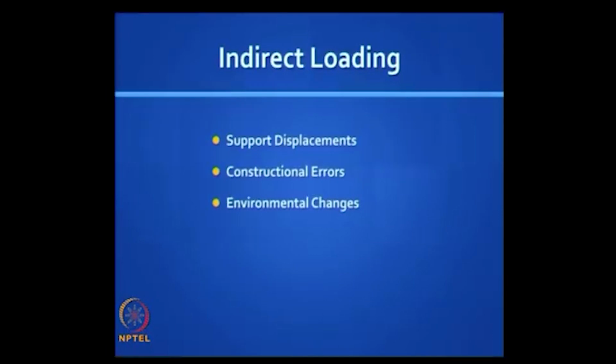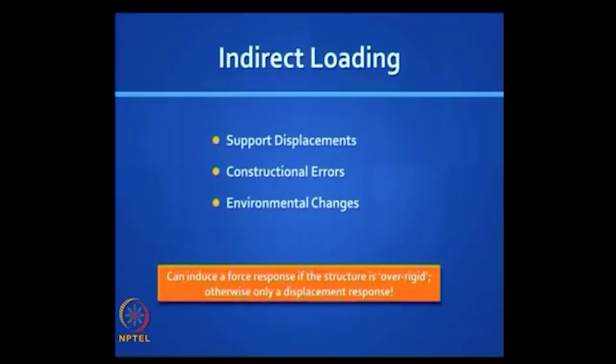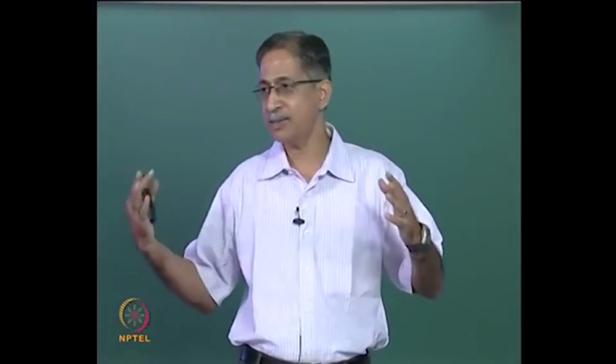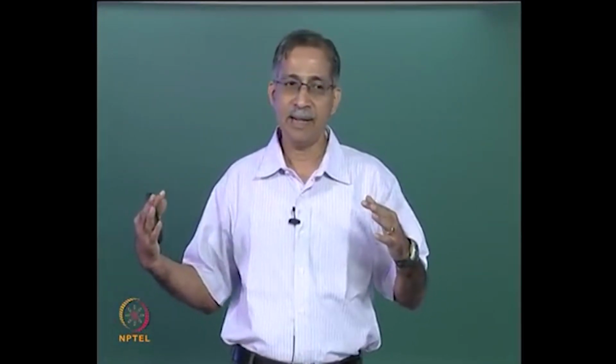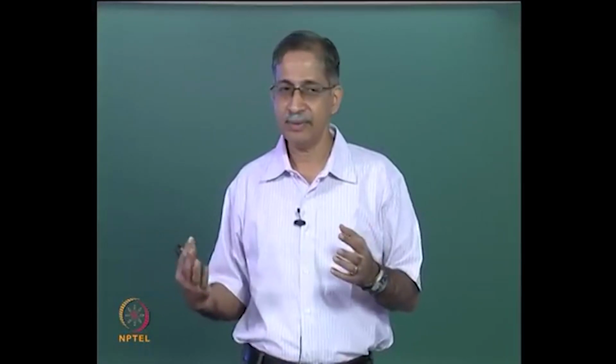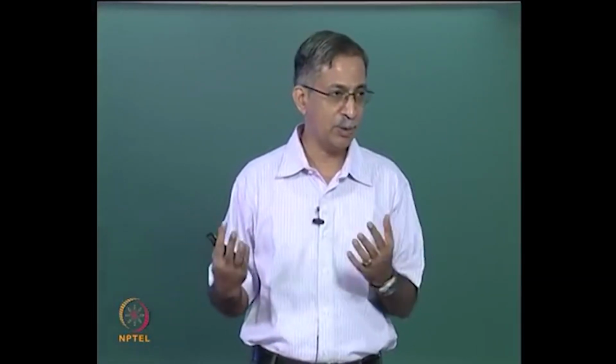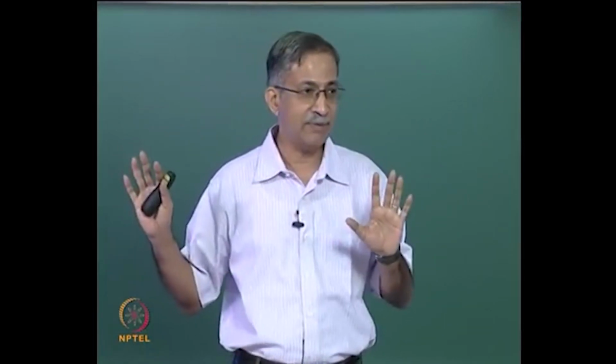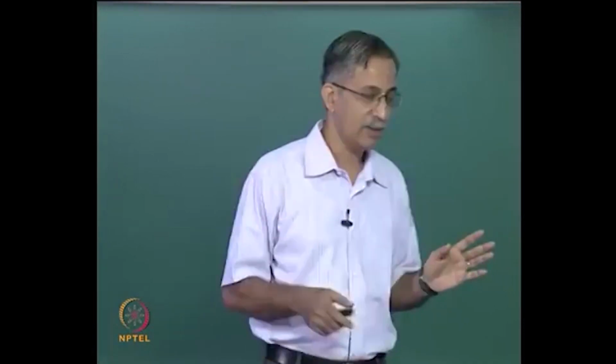Indirect loading, as we mentioned, are these 3 types, and it is important to note that this can induce a force response if the structure is over rigid or statically indeterminate, otherwise you will get only a displacement response. So if you have a simple plain truss and all the bars, let us say, had a lack of fit or they had different temperature exposures, that would cause all the joints to move and the truss will adjust itself, but there would be no internal forces or reactions.